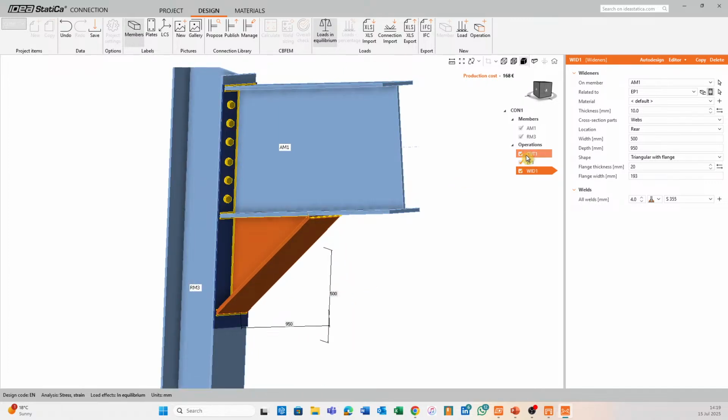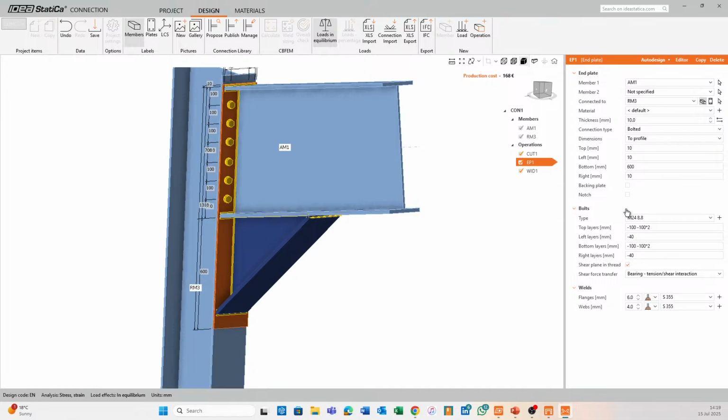All right, I'm going to go back to my end plate again. I'm going to extend these bolts. So I have to now create a positive value because these are cumulative. So I have to get from that location of that bolt, so that minus 100, minus 100, minus 100, now to a positive value of 400, and then I can say again 100 times 2, maybe even times 3.